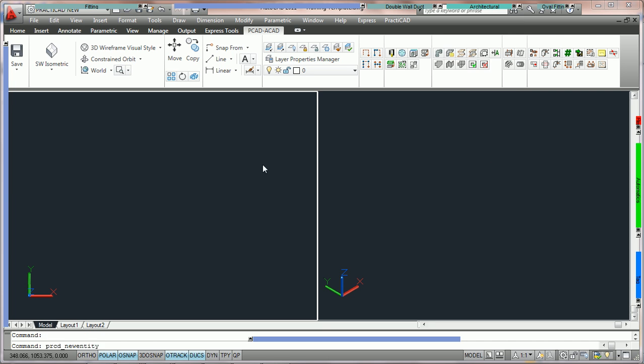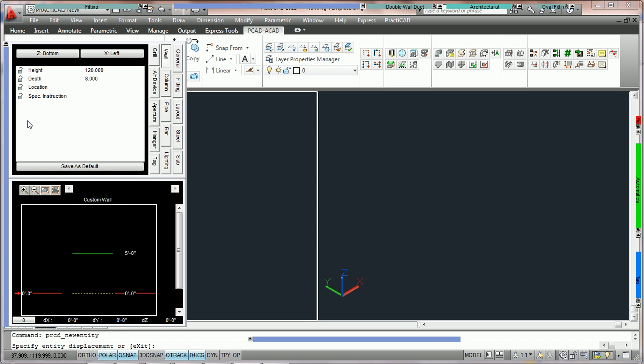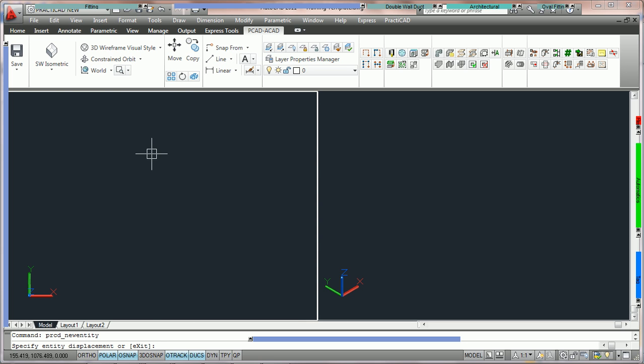We're going to pick the custom wall out of the bin and go over to the item box. Notice you have the same hold points as all the other walls. Here we're going to hold this wall by the bottom left corner, but we only have the property for height and depth. All the other parameters for arc, radius, width, length can be adjusted on the fly, which makes this the most flexible wall we have. So we're just going to click on the drawing to start our wall, and then click one more time. That's going to start the first displacement of the wall.